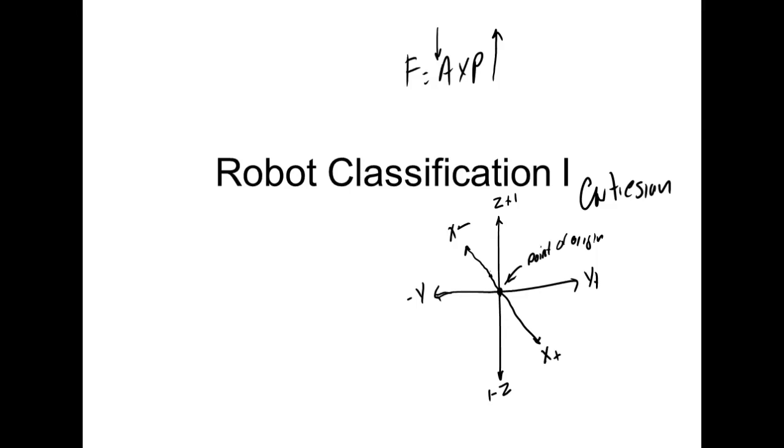So they'll say, okay, you go X so many degrees, and you go Y such a distance. So anywhere I put a point in this plane, it could be identified by these three different things, right? Understand what I'm saying? So I can identify positions by a Cartesian system, and just about all your robots have to do that. Motoman doesn't. We use what we call encoder pulses. But every other robot in here saves it in this Cartesian system.